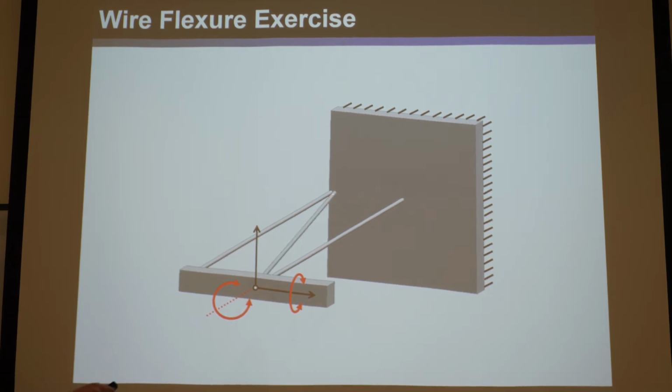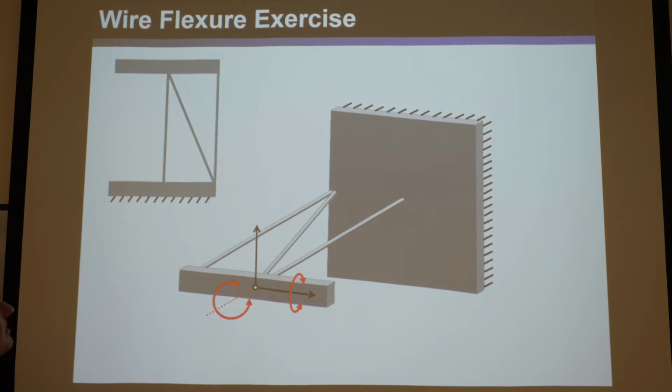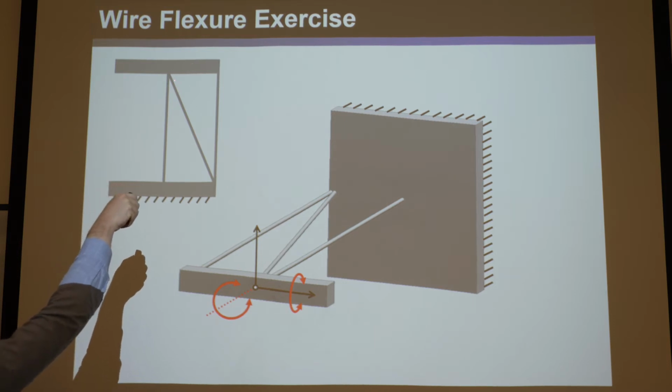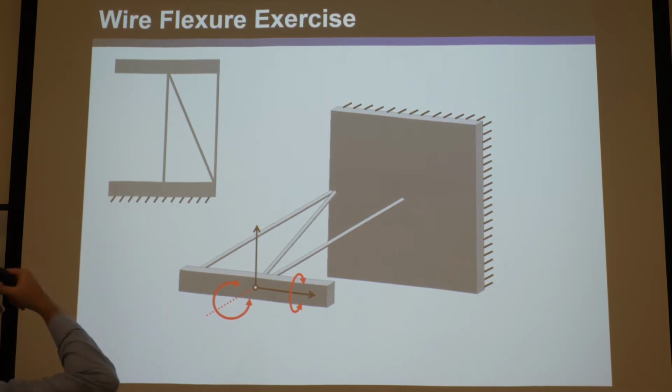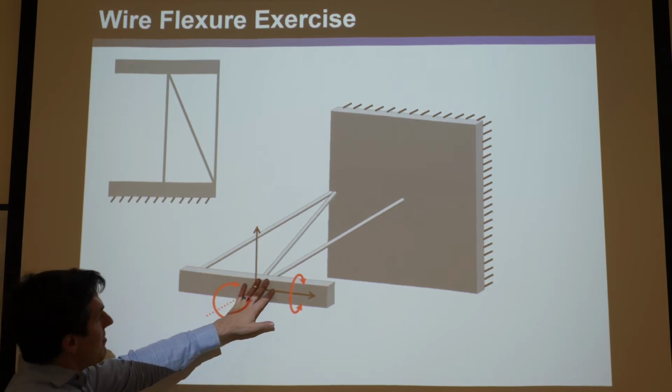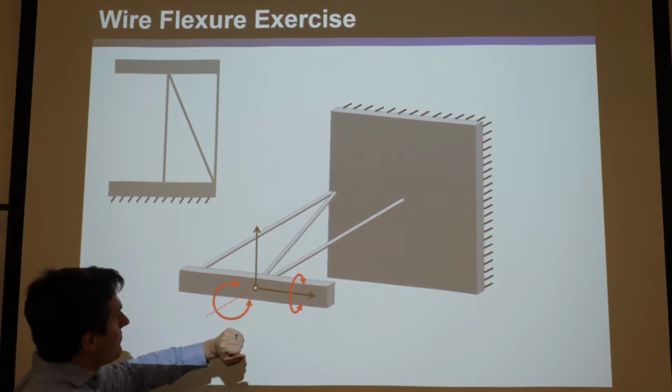All right, let's add another one. Okay, an angled one from there to there. Our brains don't like non-orthogonal things, but they can exist, obviously. So which one does this one kill? Well, imagine none of these could stretch. Well, let's actually look at it from a bird's eye view. So here's the ground, here's the stage, and this is what the constraints look like. They're all in the same plane. Here's the angled one. Okay. Well, of these degrees of freedom, which one does it kill?